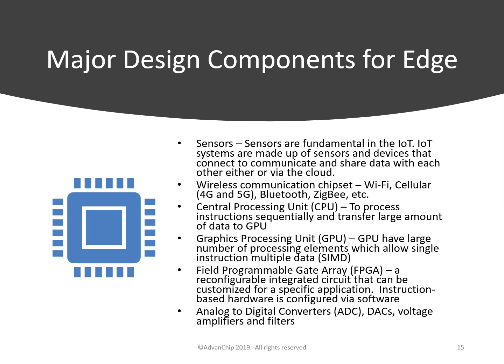CPU, the central processor, handles basic instructions and allocates the more complex tasks to other specific chipsets to get them to do what they do best. GPU is the graphics processing unit, which works well with deep neural network computation because it allows parallel computing through thousands of threads computing at a time. FPGA, field programmable gate array, means they can be configured by the user after manufacturing. FPGA contains programmable logic blocks that can be wired in different configurations.